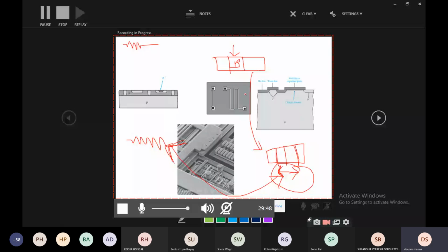So here in base implantation, we are implanting a very thin N-type resistor channel, right? And also we are implanting a very thin P-type layer. So here in this we are having a PN junction, right? In the base only we are trying to create a PN junction, and you just try to reverse bias this junction so that it will behave like a resistor.